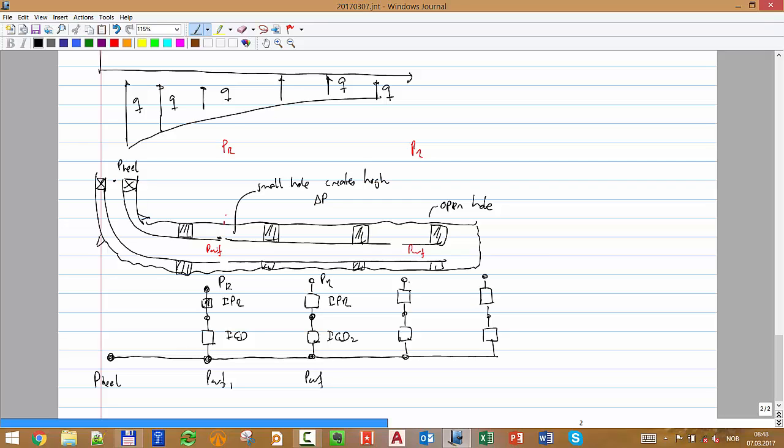And of course, here I haven't told you the full truth, but this hole I cannot make exposed directly to the open hole, because here I might have crumbling problems. That wall might crumble, and you might have plugging. All of this sand might damage and cover my hole. So I also need, sometimes I use a slotted liner, or I use a mesh. Okay, I try to make, and we will see just one wire mesh.